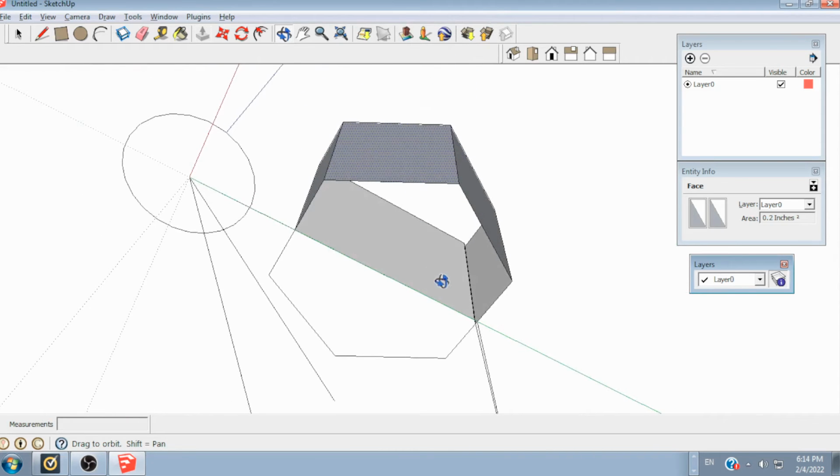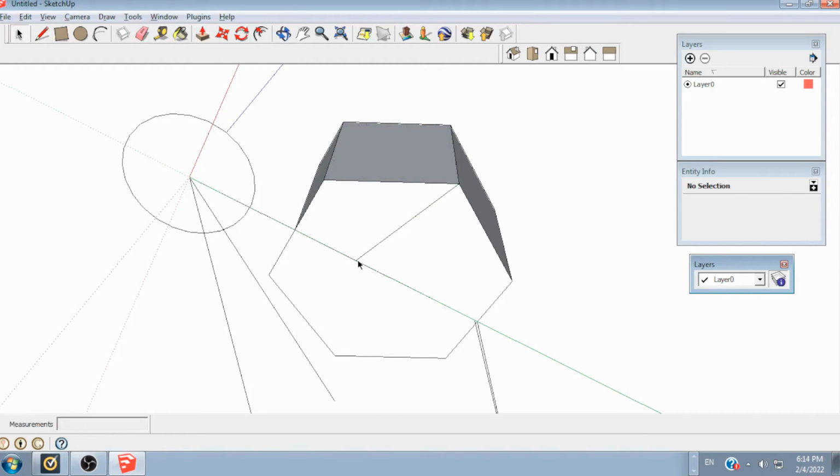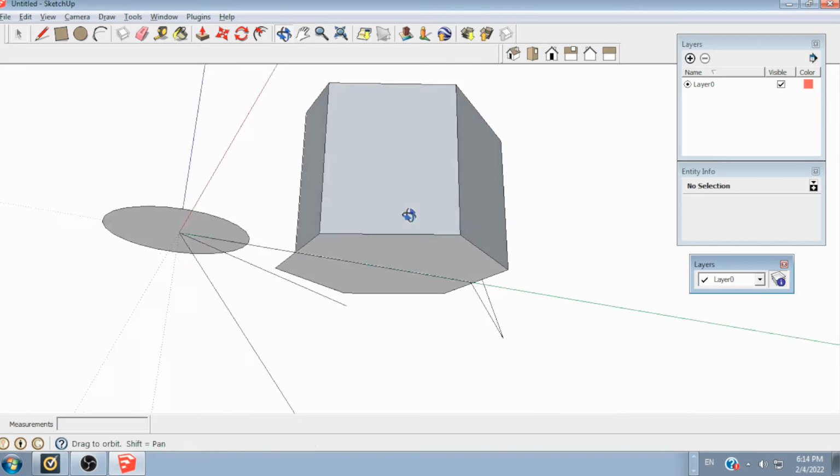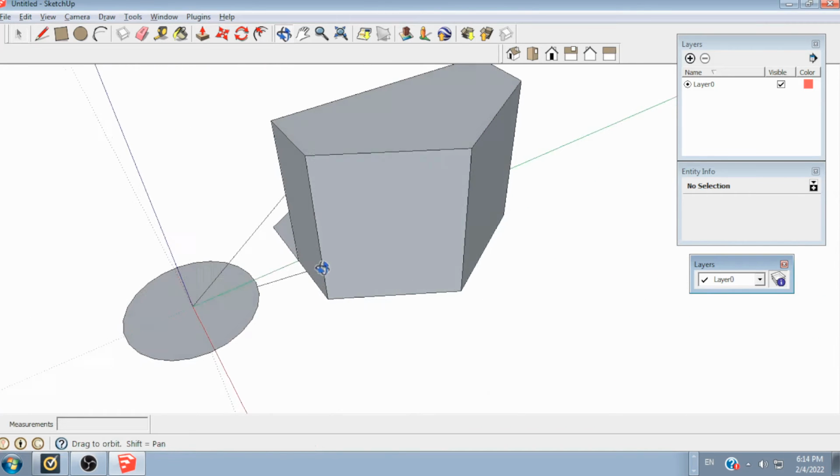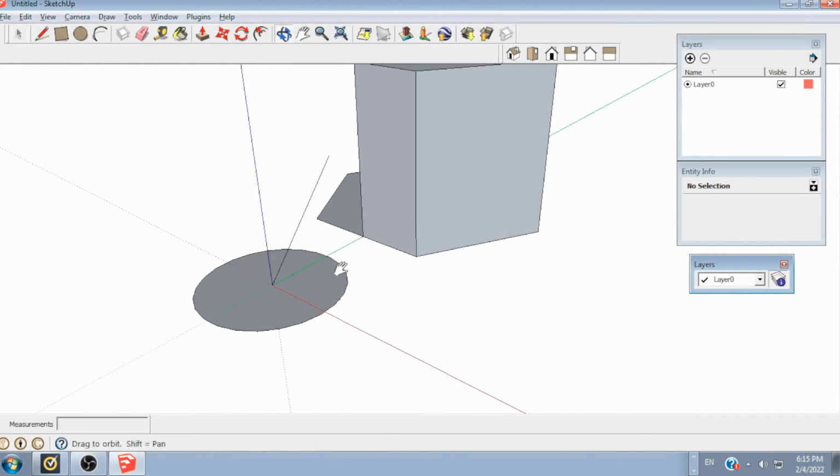Oh, a simple way of closing a surface is to hit L and then draw a line from any of the 2 points. It magically closes it, and I can go back in and left click and delete the line. All kinds of tricks like that. I won't say many of them now, but there's one that I particularly like, and I discovered this fairly recently.